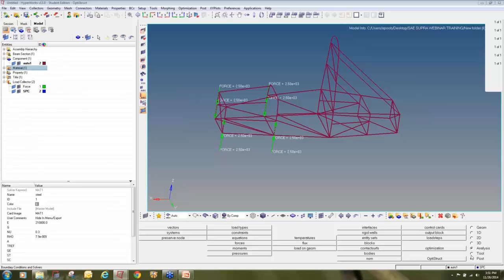So what in torsional analysis, what we are going to do is, we are going to hold a chassis either from rear or from front and try to twist it. So torsional rigidity tests can be performed either on front section or the rear section. So the process will be same, but it depends on you how you want to perform. But you have to perform in both the direction, that is in clockwise direction and anti-clockwise direction.